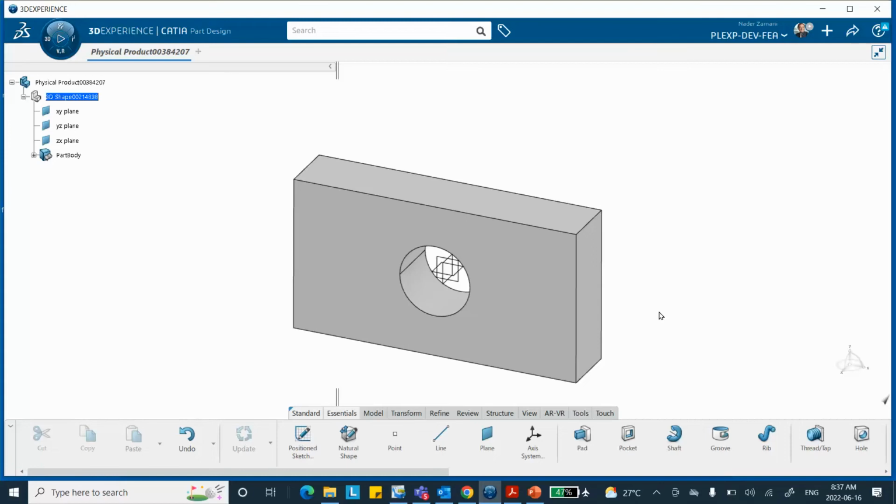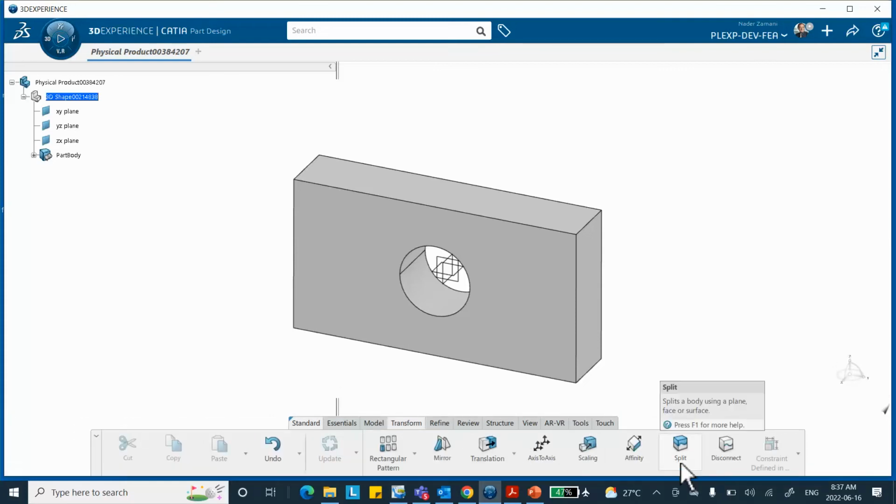Splitting it. Well, the split, you have to become familiar with some of the stuff that is in these tabs. For example, if you go to transform, split right there. It's not a saw anymore. It looks like that. Okay, you click on it and you read it carefully to see what it says. Down here, it says splitting element. One of these planes, for example, this one.